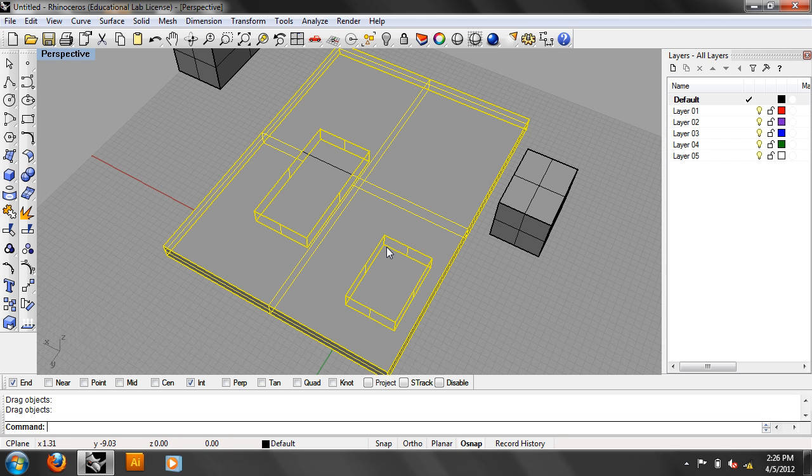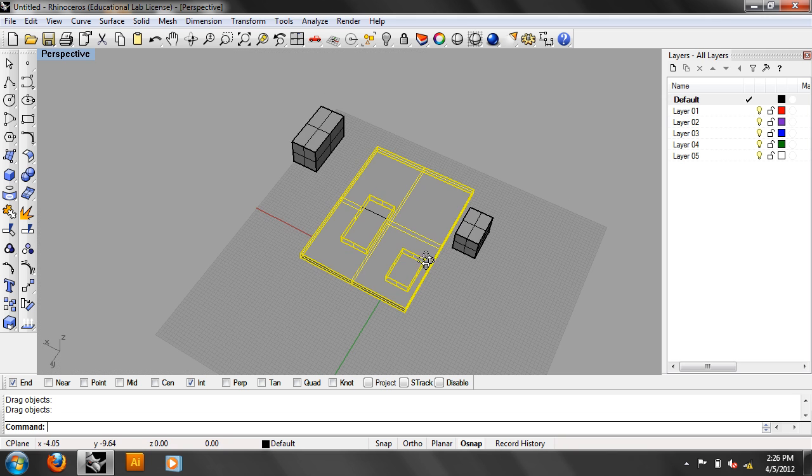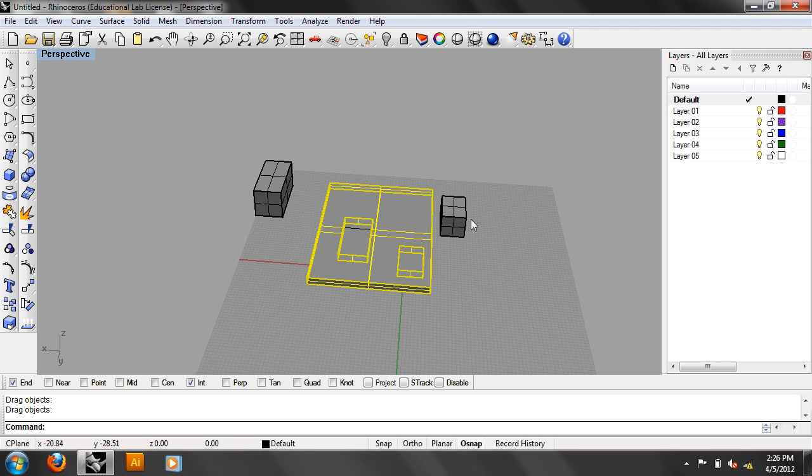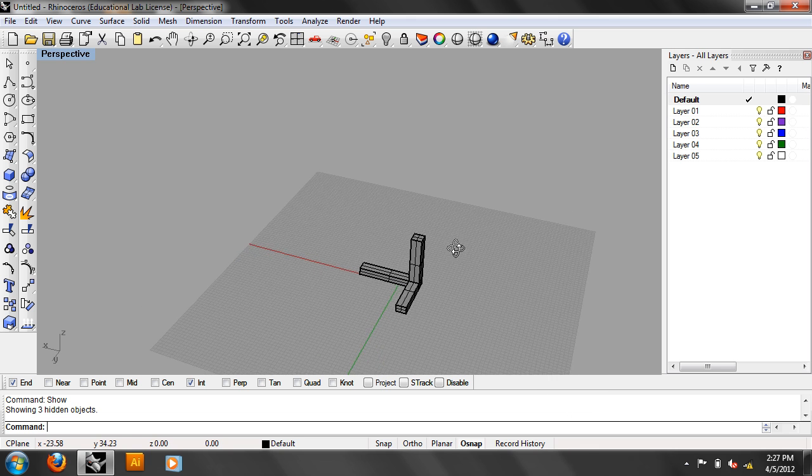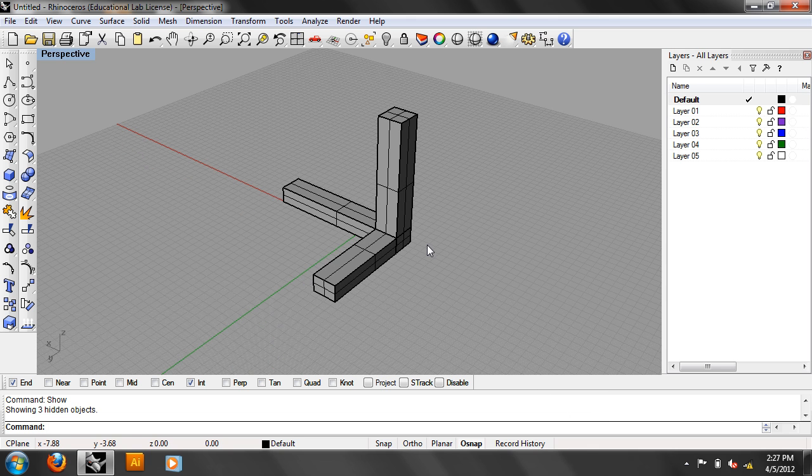Okay. So again, I don't want to say that you can't ever use it, but I want you to have other tools in your belt. There's nothing that you can Boolean that can't also be done by just taking a geometry, splitting it with another piece of geometry, erasing the surfaces, and then joining everything back together again. That sounds complicated, but that's actually what I'm going to do. The complexity of the geometry doesn't matter. It's the amount of automation that you're asking the computer to perform.